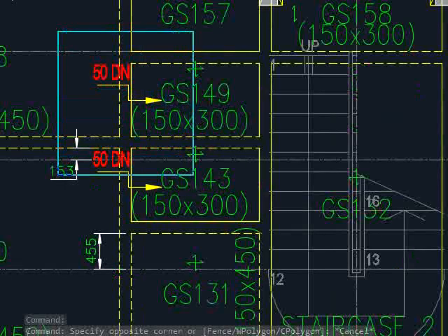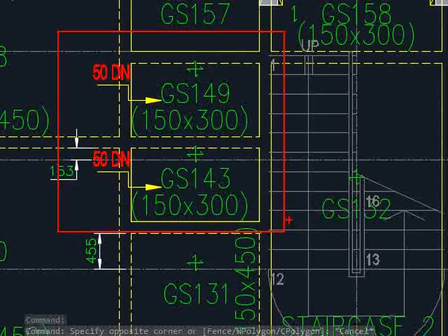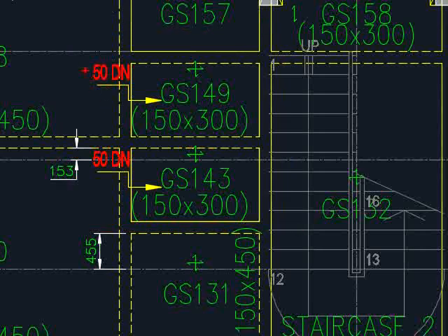Another common place you will have the drop is at the bathroom or the toilet, where there is a 50 mm drop, and such a drop will lead to contact with water, which you need to consider for the water leakage issue. Whenever you have something like this, make sure this slab is laid with a double layer of reinforcement, and more reinforcement is to be provided in order to control the crack width to prevent the leakage of the water through the slab.